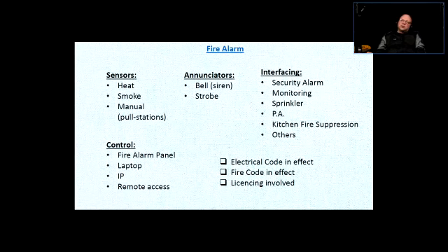Okay, so I talked to you about the wet sprinkler system. Now, sometimes what is called a dry sprinkler system is implemented, depending on where they're installed. If the system is installed in a building where regular heat is supplied and the temperature is at a certain level, the water doesn't freeze. For the most part, it's the most efficient system because the water starts coming out right away. So it will be a wet sprinkler system because the water is present in the pipes all the time.